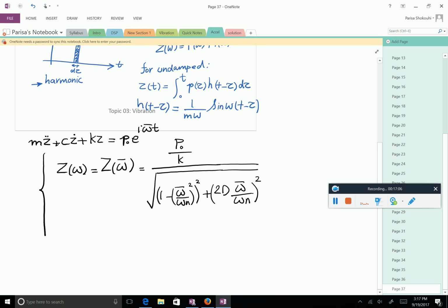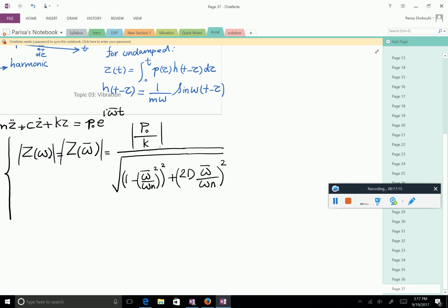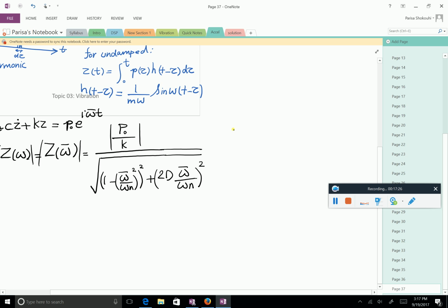This is, of course, the amplitude. So, if you want to see what is the effect of this dynamic loading, we saw that we can actually look at the response of the system and normalize it by the static response. Why do I call this a static response? Because it's just force amplitude over stiffness. That's displacement. If there was no omega bar involved, that's just a static response.